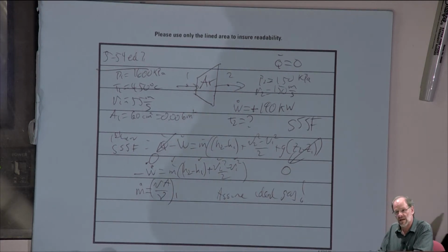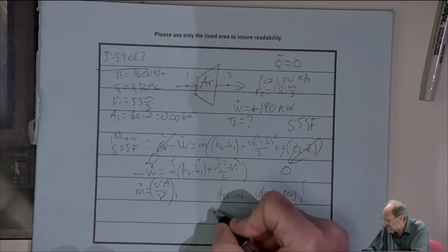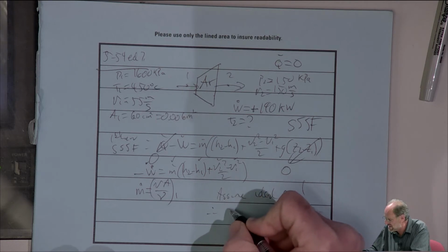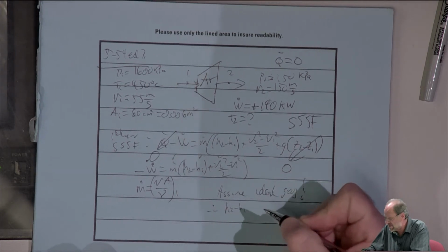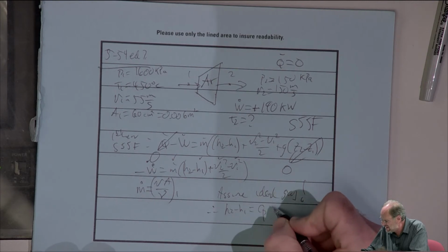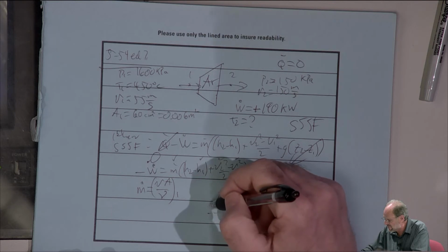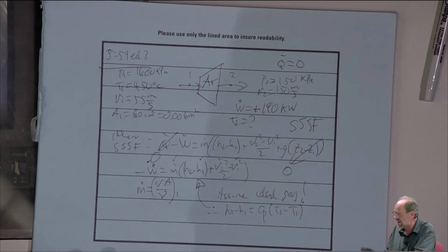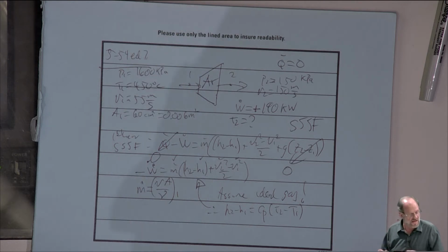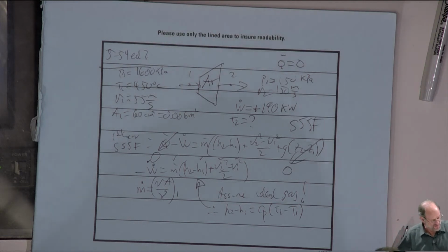And since it's an ideal gas, we know, therefore, that any enthalpy change is going to have to equal Cp times the temperature change. So we're going to have to plug that back into the first law above. In fact, that even makes the problem easier, right? If we can find the value of Cp, then we should be able to solve for my one and only unknown, which is just going to be the temperature. But here too, there's another little bit of a problem, and you're going to have to kind of get used to these problems over time.